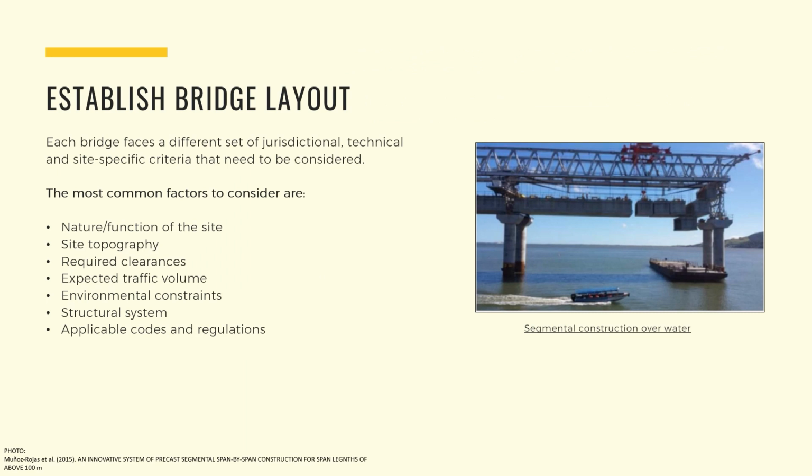Establishing the layout is of most importance when working on bridges. As the designer, you have to factor in that each bridge or site faces a different set of jurisdictional, technical, and site-specific criteria. Some common factors that are considered are the nature or function of the site, topography, the required clearances, especially if there are any roadways or waterways under your bridge, the expected traffic volume, environmental constraints, the structural system that will be used, and all applicable codes and regulations.